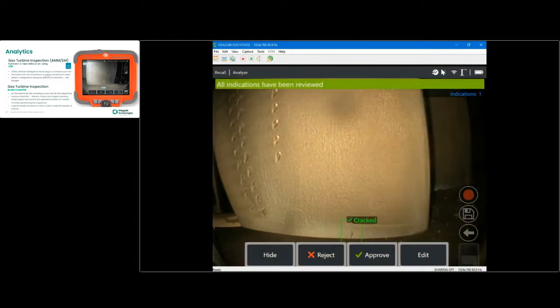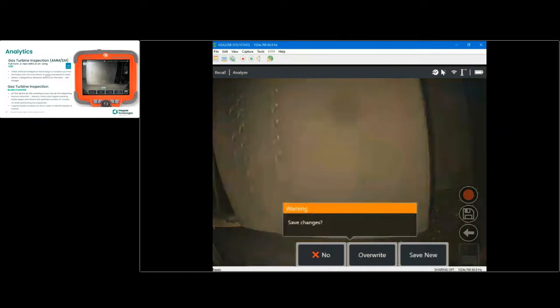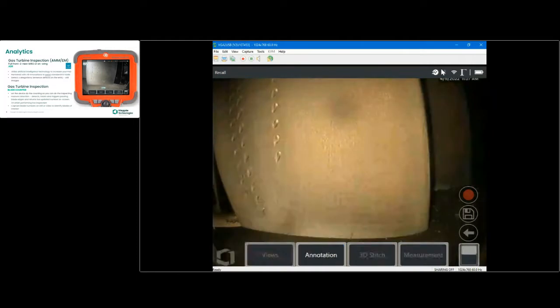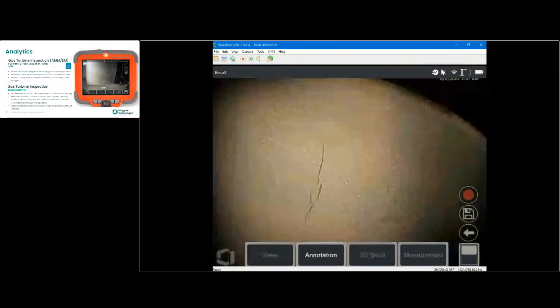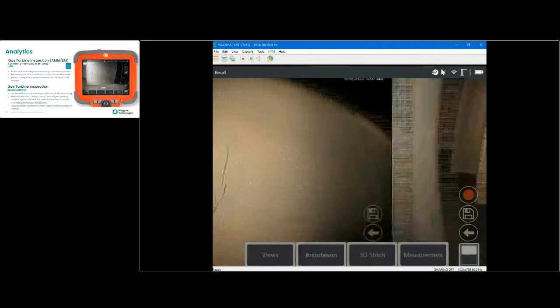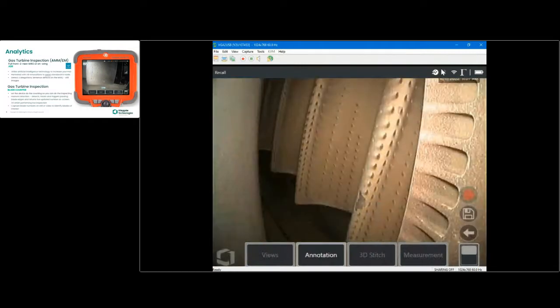So it's very easy to label and carry out that activity very quickly once you tap the screen. As you're going through your inspection, it's very easy to tap, tap, tap, and just check, check, and check as you're going through. I'll just show some other images from the combustor. So some more defects here, and there we go, press Analyze. Very quick TBC loss.